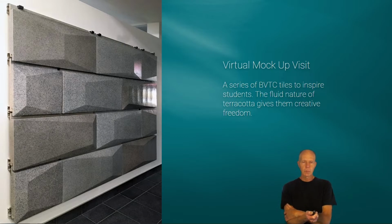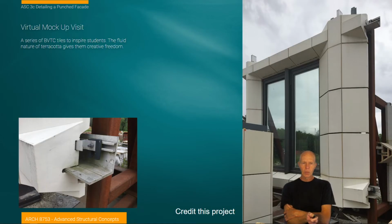It could have a heavier footprint, but because it is a fluid material, you can actually generally shape it into anything. So in this example here, we have a rain screen system. These terracotta tiles are actually not extruded, but they're formed in what's called a ram press. So their shape is generated by pressing them into a mold. And you can see now that you can create all kinds of variations in the kind of patterning with it.